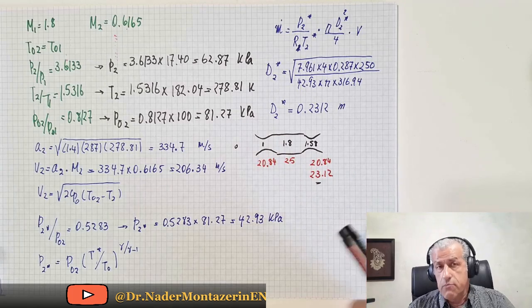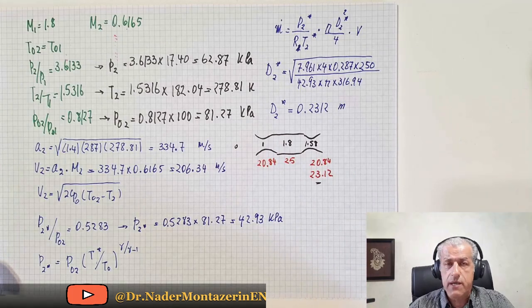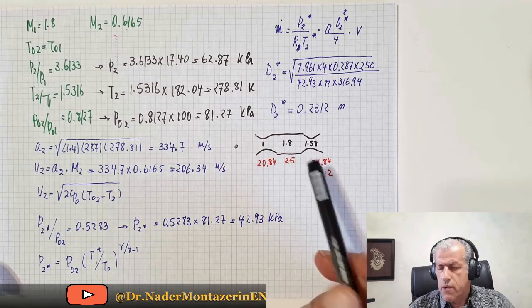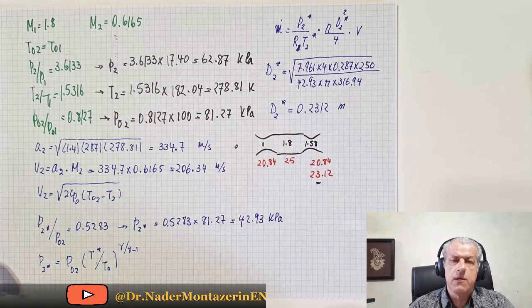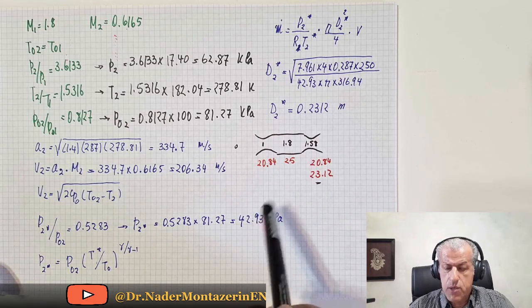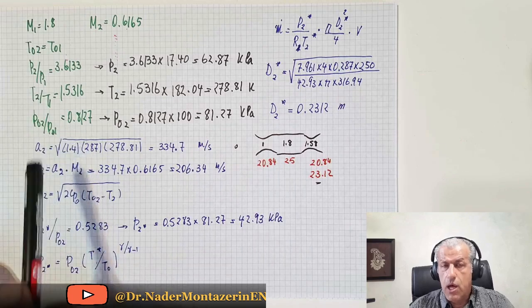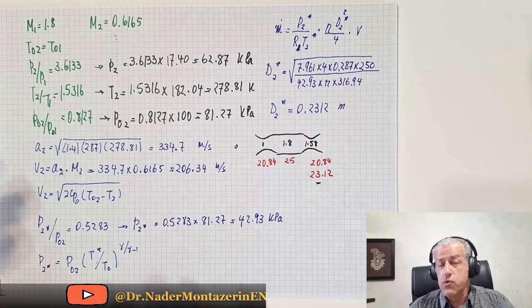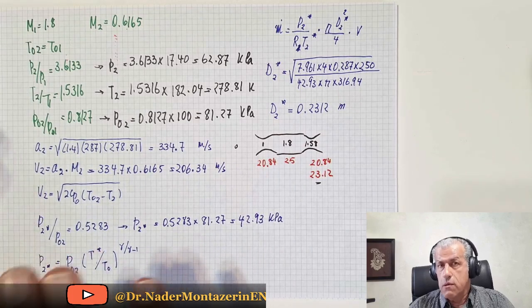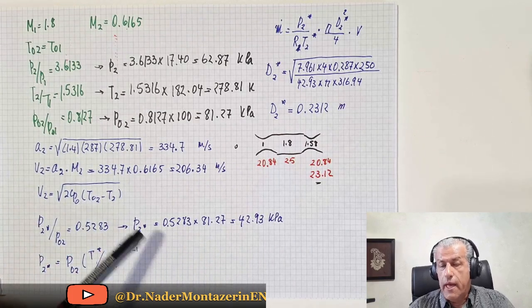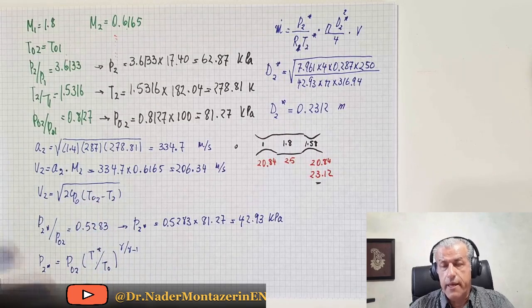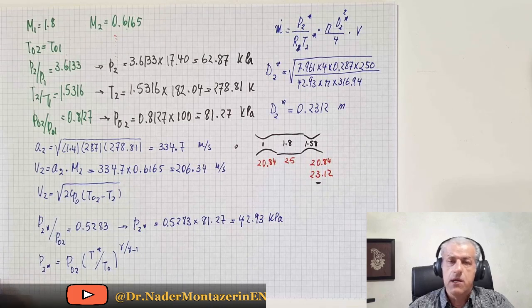In many real wind tunnels, up to Mach numbers 3 or 4, they don't bother with such a supersonic diffuser, and the total pressure drop would not be prohibitive. So it would be still very good to accept this total pressure drop, get away with the supersonic diffuser, and just reduce velocity with a normal shock wave.